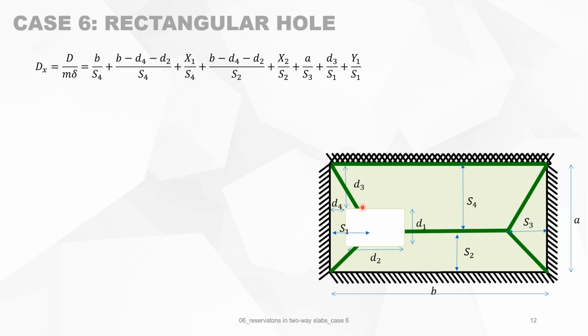It's not a portion of x4 like we've done with the calculation of E, because now we are taking into account the angle of rotation. So when this piece of slab portion is rotating here with an angle delta, this is the same for every part of the slab. So that's why I divided by s4, which is the distance from there to there.